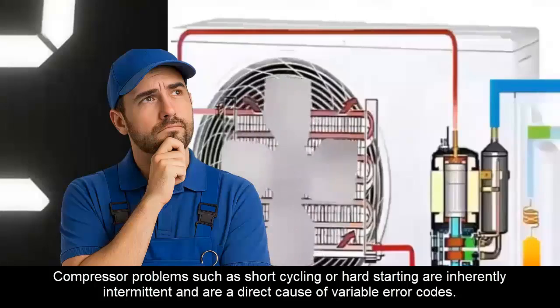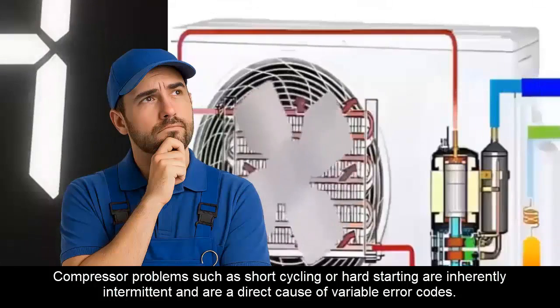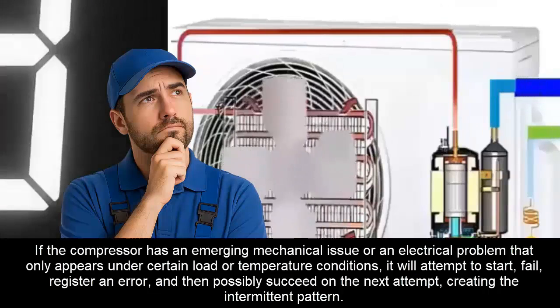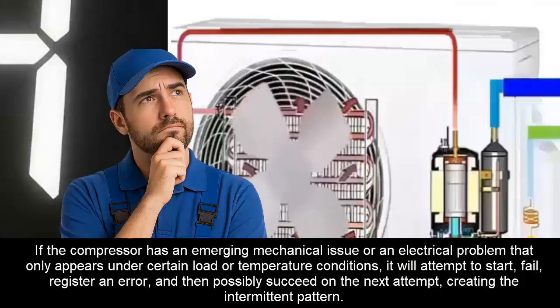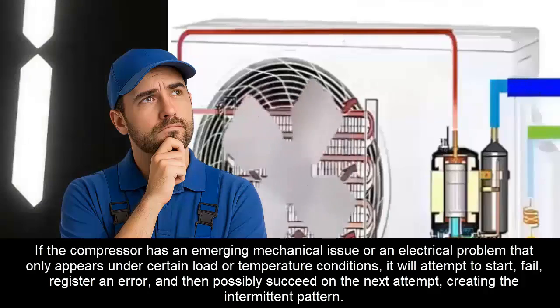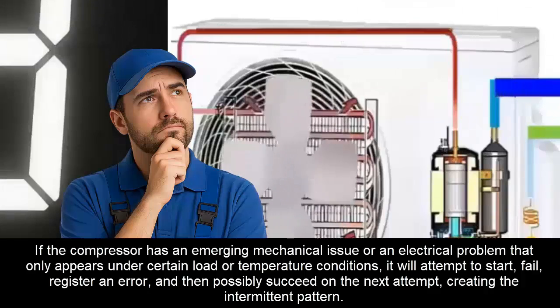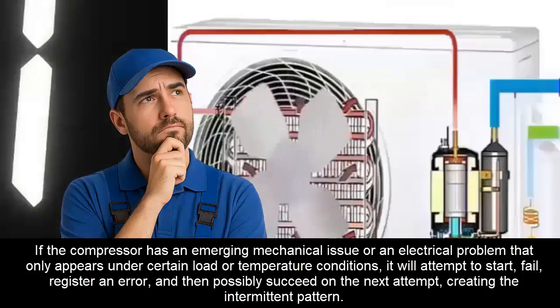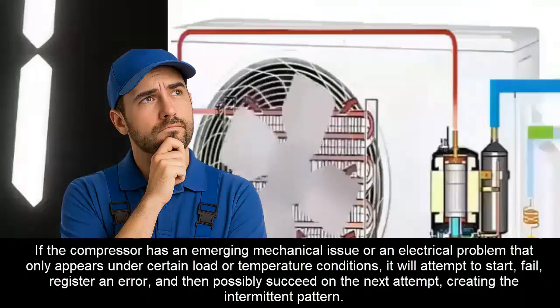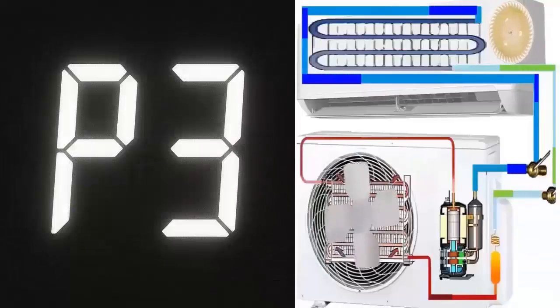Compressor problems such as short cycling or hard starting are inherently intermittent and are a direct cause of variable error codes. If the compressor has an emerging mechanical issue or an electrical problem that only appears under certain load or temperature conditions, it will attempt to start, fail, register an error, and then possibly succeed on the next attempt, creating the intermittent pattern.